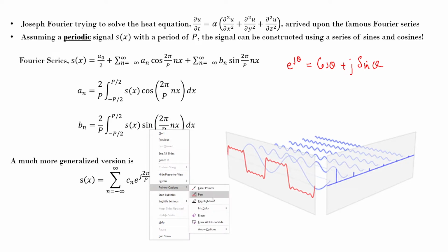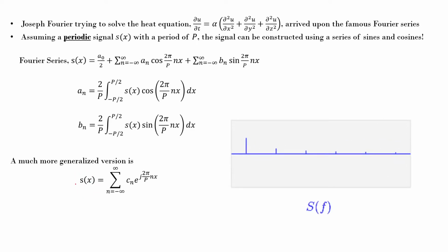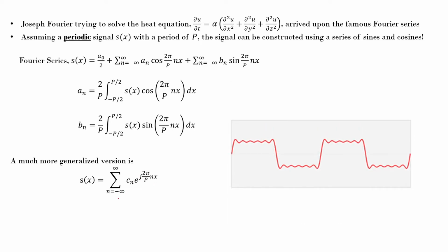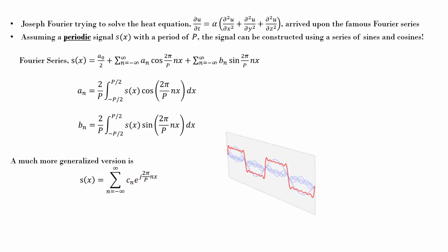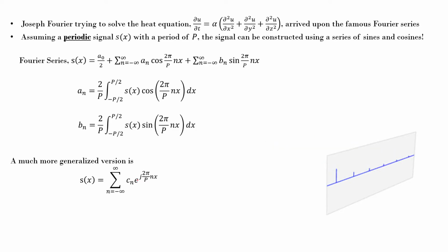So let's take a closer look at this formula. Essentially what it says is that there is some signal and you are trying to represent that signal in a complex sinusoid, that means a cos theta plus j sin theta sort of representation. And for each of those, when n varies you have a different frequency sinusoid. The Cn stands for the weight of that particular sinusoid. So what does it essentially mean physically? My signal, let's take a square signal, will obviously have different sinusoid components, and what is the value or weight that I put.